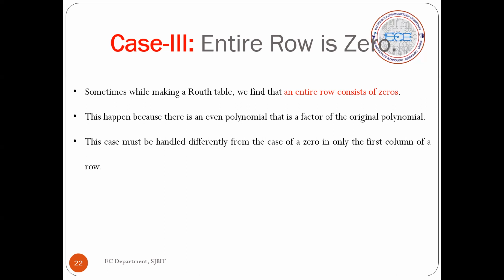Once we could complete the Routh-Hurwitz table, we used the conventional technique of observing the first column sign changes in the elements. Based on that, the stability comments were given. What was the second solution given for case 2? In case 2, we used to reverse the coefficients.